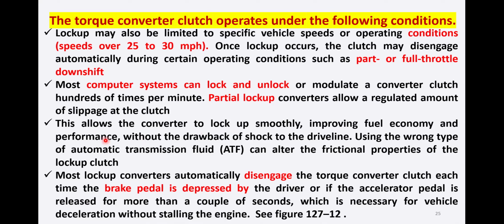Using the wrong type of automatic transmission fluid can alter the friction properties of the lockup clutch. So the transmission fluid which the OEM has specified, you must always use that transmission fluid. Don't try to change that transmission fluid with the advice of the local mechanic, because the OEM has specifically designed and suggested that specific transmission fluid, as otherwise it will alter the frictional properties of the lockup clutch.